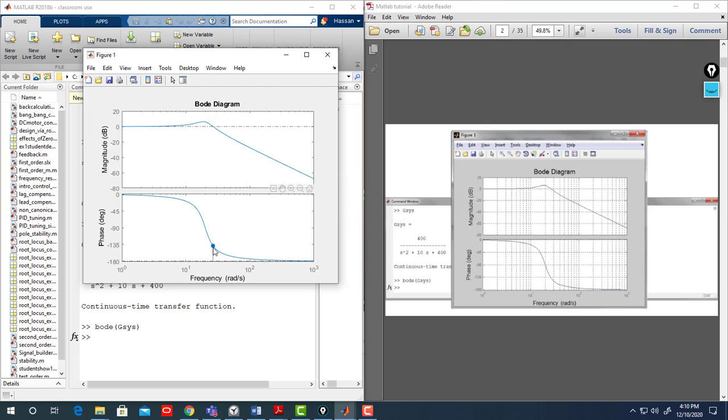Here the phase margin is the minimum stability margin, which is 41.4 degrees, and you know how to find it, how far we are from the 180. And the system tells you if it's stable on closed loop or not. It is above the 180, so it means it's stable. It should have both above the 180.